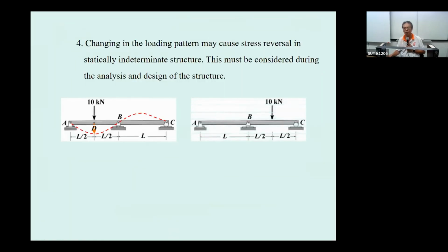Also, when the load changes, the deformation of the structure changes. If this one is reinforced concrete, in this way you have to put a lot of reinforcement. In this way, extra reinforcement, and also this way and this way. So for the indeterminate structure, don't forget to consider different load patterns in your analysis and design.